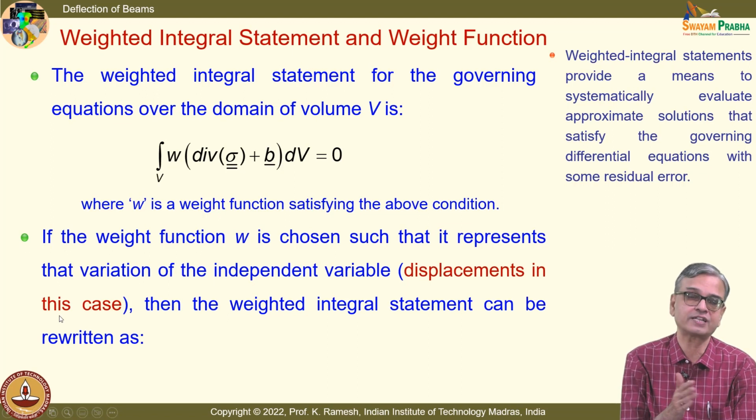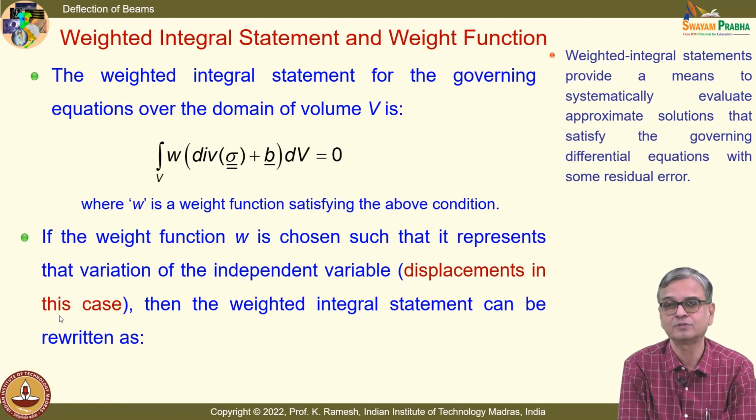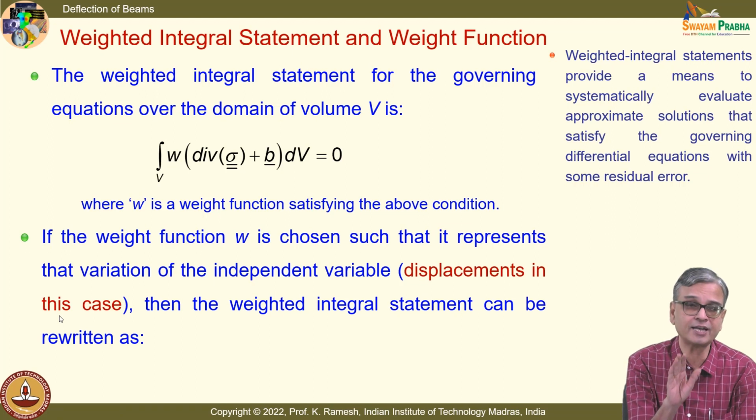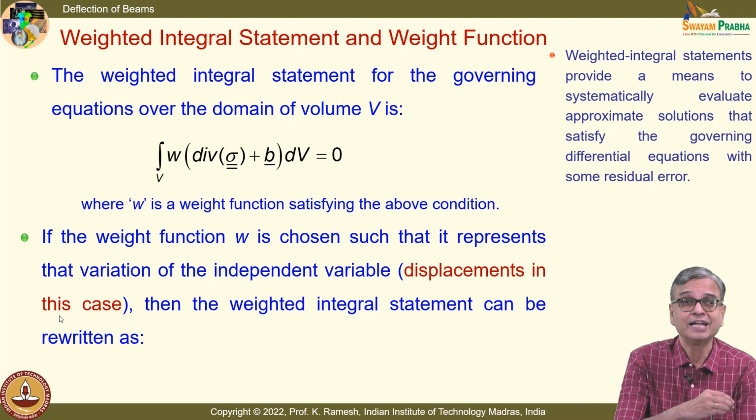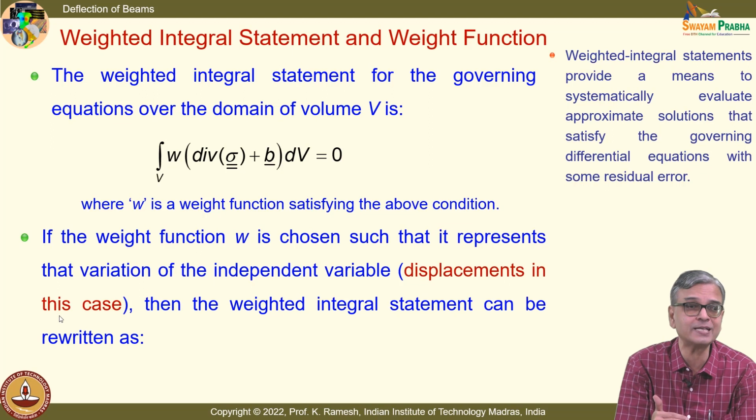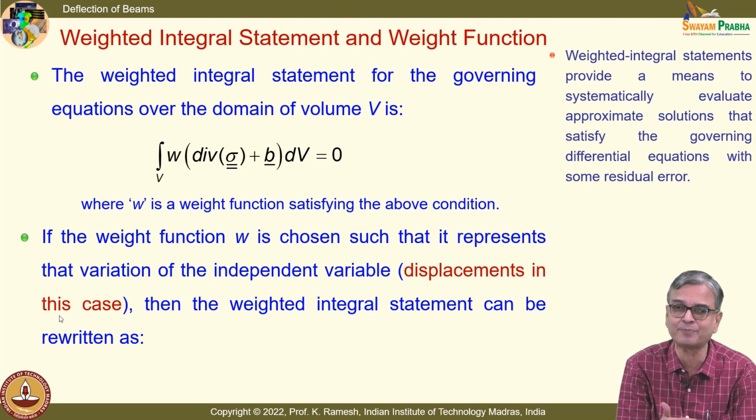See, in the case of strength of materials, what did we do? We took cross sections and loading in such a manner that you can visualize the displacement. In a complex problem, you cannot visualize the displacement. Theory of elasticity helps you to solve the differential equations and evaluate the displacement by solving it as a boundary value problem.